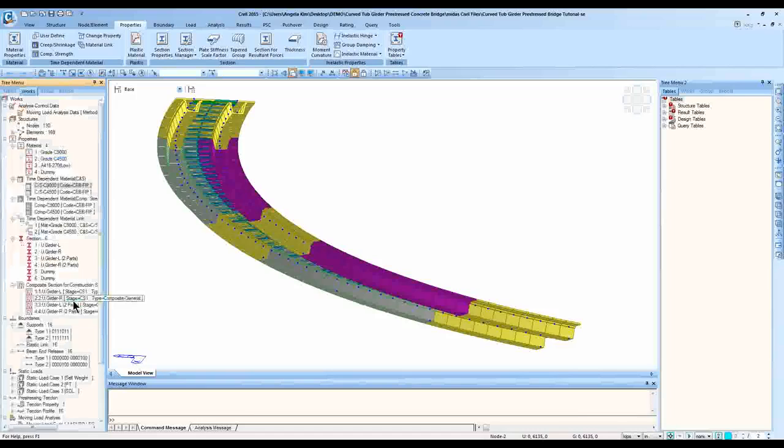Okay. So this is how you have the time-dependent function run, and how it's going to work simultaneously with the construction stage analysis setup. We define our function, but it's one function, so how does the program know when the girder is activated and at what point of the time dependency the function is at? How are they all working together?